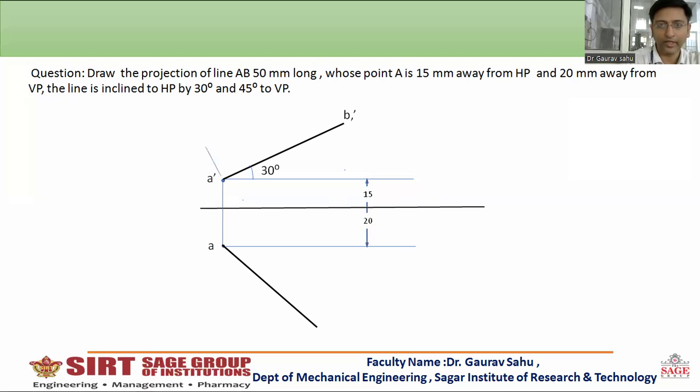Here I'm marking the true length because we have to show that it is true length, and this line is also true length, dear students. So now I have marked A B1 and A dash B1 dash. This is true length and this is also true length. I'm not marking it below as I've already marked above, and in graphics these kinds of abbreviations notify that this is true length or this is the front view. So in certain cases you don't have to mark true length every time. If you want to mark it, you can mark the true length over here in this manner only.